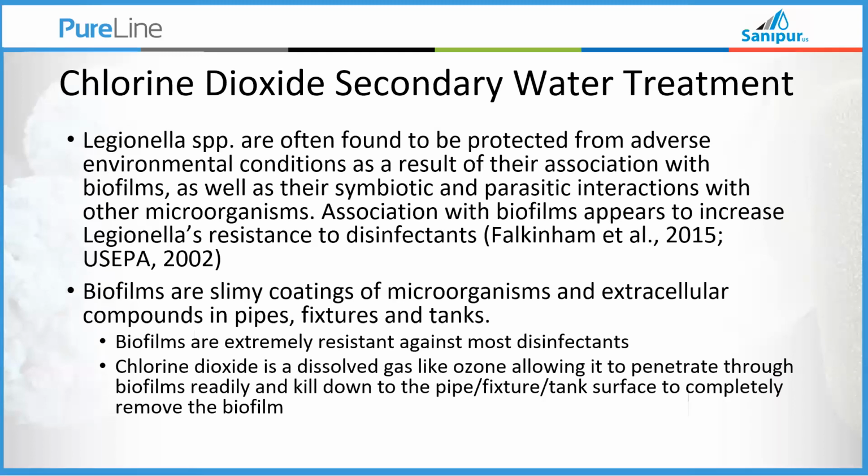Legionella is often found in biofilm. We've discussed this, and it offers it a level of protection, and that's why we have to talk about these specialty chemicals in order to eradicate it. It's why the chlorinated water systems that supply water still don't eliminate the problem. And again, it's why chlorine dioxide is one of those few go-tos that will work, is that much like ozone,